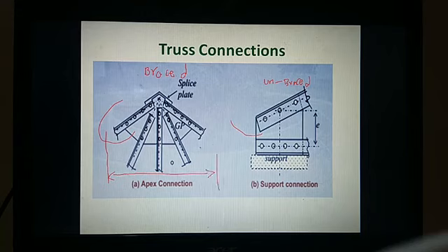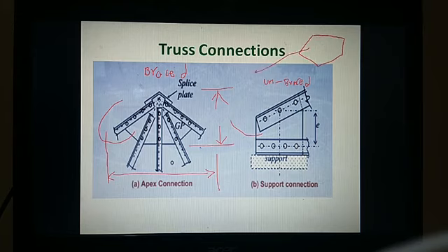Based on how many members you are connecting, you can take the length and the width. That's why if you see the gusset plate in real applications, it never has a defined shape. అర్థమవుతుందా? మీకు గసెట్ ప్లేట్ రియల్ అప్లికేషన్స్లో ఎప్పుడు ఒక డెఫినెట్ షేప్ ఉండదు. It will be like this, an irregular shape, and in this irregular shape your members are going to be connected like this. అర్థమవుతుందా? ఇలా కనెక్ట్ చేస్తాం. Okay, so here the importance is only the thickness, not the width and length.